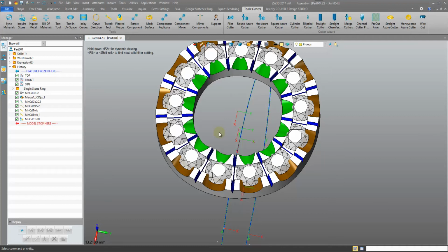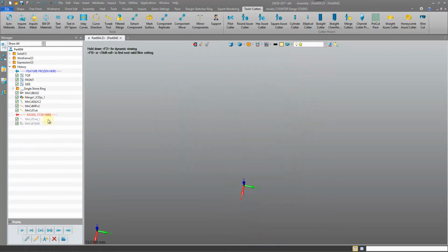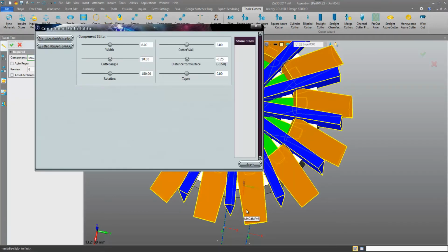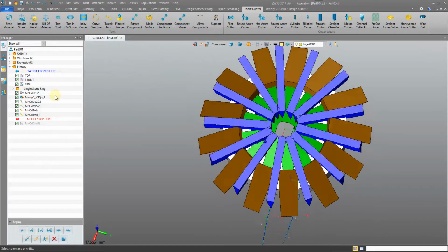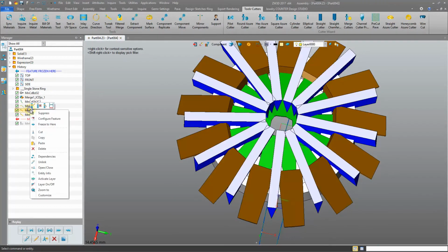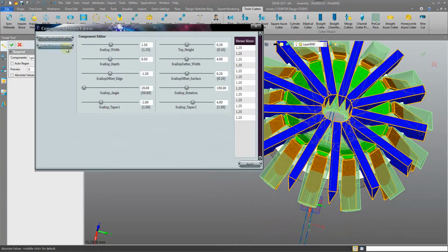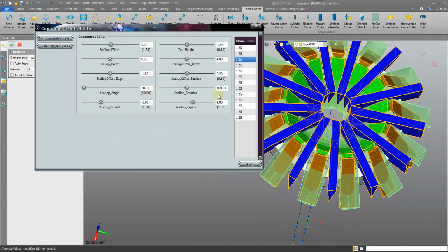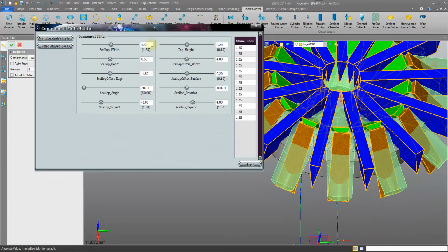The one thing I want to point out, however, is that if you ever want to modify your cutters again, you will know that you can just apply another tweak tool to the cutters and do it again. But I've always found that that can sometimes create complications. I do like to just modify the original tweak. If I want to change the scallop cutters, I'll modify the original tweak. Do not activate it again, you'll overwrite your values. Just tweak it, make a tweak here to whatever it may be, and confirm.